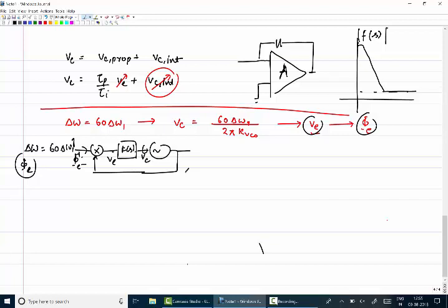You do not have to give a small step and wait for a long time. Okay, this should not be confused with the following. If I am using a VCO and I give this VC value as, let's say, I want something as 0.7 volt in a steady state. Okay, so I give this 0.7 volt and have my FS here, and I let the loop operate. This should not be done in this manner. Let me show you.